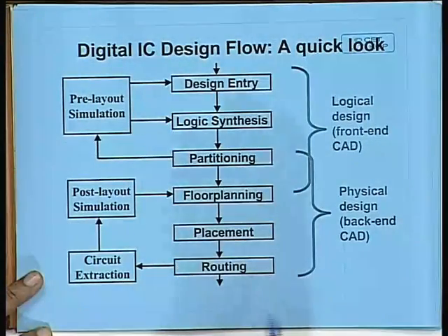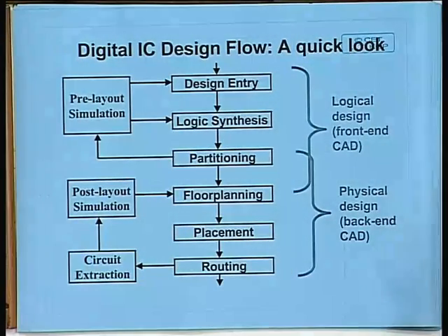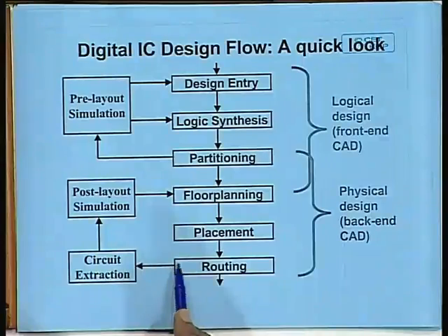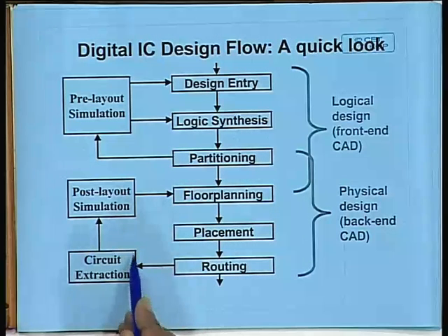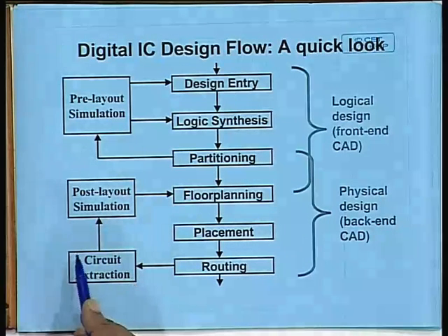But as you know, the process of fabrication is expensive. If you give a chip for fabrication, it may cost you several lakhs of rupees. So before going there, you must be sure that your layout is also correct. So normally you go through a process called circuit extraction.